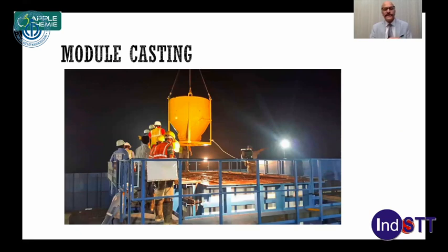What gives you a benefit is, if you look at the overall construction, friends, that when you are doing a building construction, maximum time is spent in the service area, because in the toilets and washrooms you have electricity, water, service lines, plumbing, hot water, cold water, so many things. But if you have all the things already embedded in the service block, and the service block is made ready with the sanitary fittings and brought directly to the site, it saves a lot of time and makes a lot of sense. So that is one plus point of precasting.